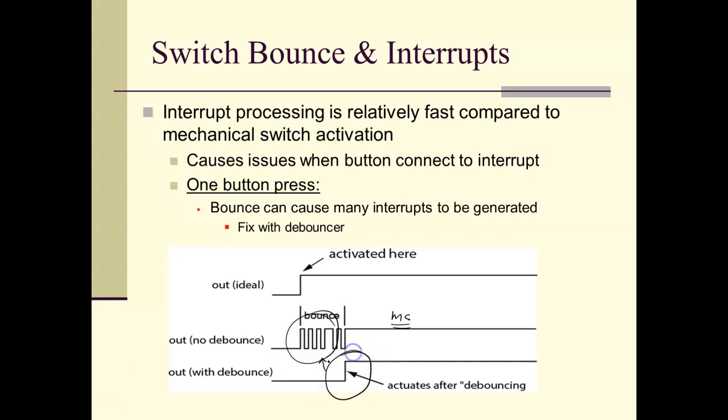So what you're going to do is debounce it, clean it up. Your signal looks like that. The drawbacks are you're going to have to provide extra hardware if you do it in hardware, or extra firmware if you debounce it in firmware. And there's also going to be a delay. You think you press the button here, but it doesn't really get pressed until that time. Typically this is a little bit of delay you have to deal with one way or another.